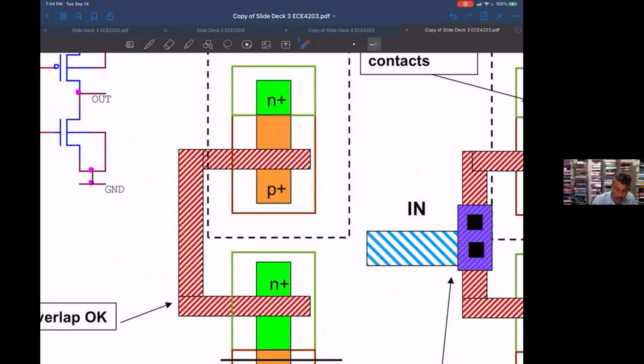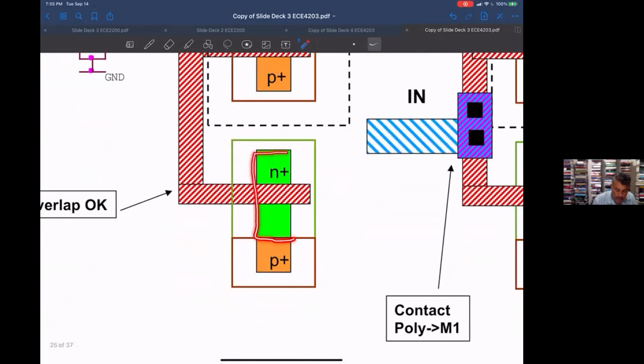If I want to make this a wider transistor, as I think I talked about in slide deck 5, the video from this, if you make this a wider transistor, you can have more drive strength, more current output out of this transistor. So you would draw it basically wider. You would extend this P+ and extend the poly out here. And this is an NMOS transistor because I've got a poly overlap to this active. And again, this is the length and this is the width.